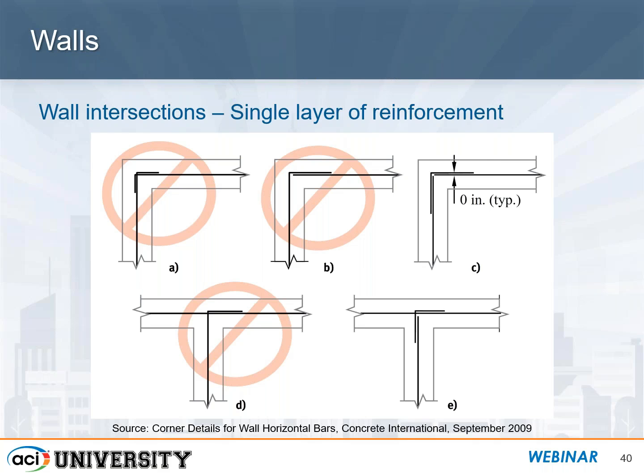So in lieu of using hooks at the ends of the bars, what we recommend, both for these L and T-shaped walls, is having straight bars come in and then have a separate loose bar that hooks around at the same location of the horizontal bars. They get tied to those, and that provides adequate development at the corners. So similar for the L-shaped, you have your T-shaped.